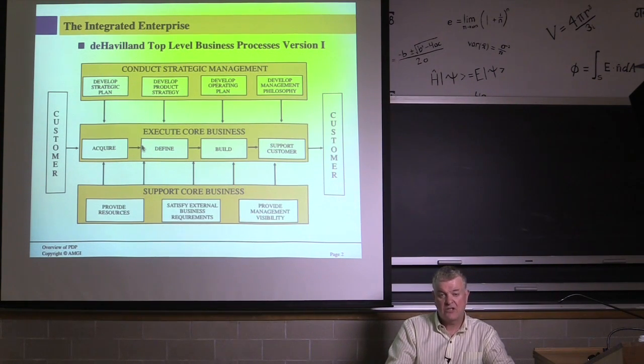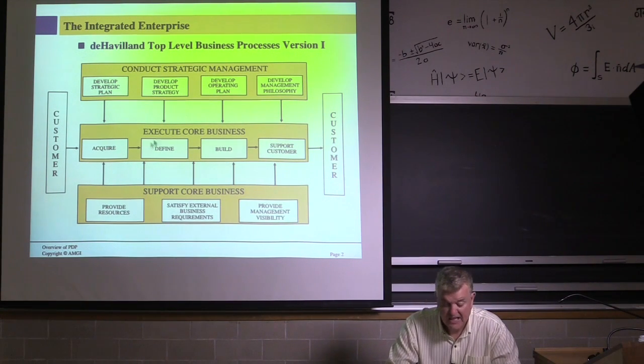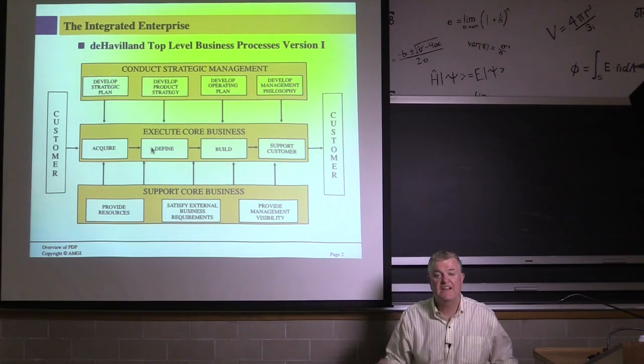design engineering. So in terms of an aircraft, it would be flight dynamics who establish the lift requirements of the aircraft, the propulsion systems, lift-drag ratios and so on. All these various mathematical relationships have to be established before you actually design the airframe. The airframe has to be reasonably well designed before you design the assembly tooling, and before you design the inside of the aircraft, before you design how the wings get attached to the main fuselage, the tailplane configuration, the flaps, the ailerons.